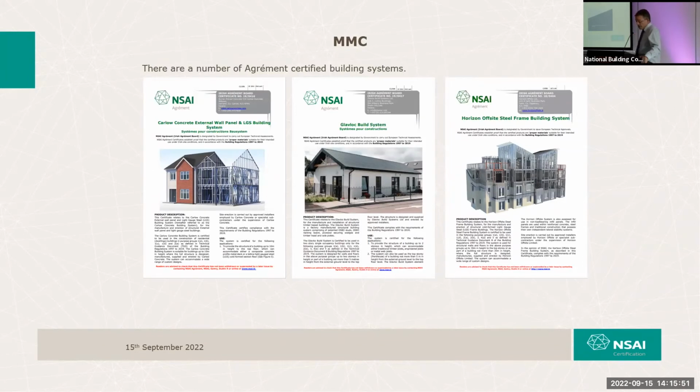Again, it's been said on numerous occasions, if we can just take the accredited construction details and demonstrate equivalence to them, which is a simple process of comparing your detail with an ACD, establishing that the minimum thresholds as described in the ACDs have been achieved, say resistance levels of insulation at window jambs, sills, heads, at pinch points where we have throating at, say, an external wall eaves junction. Not very difficult to do, doesn't necessitate thermal modeling at all, Andrew. And we can go to this advantageous Y value of 0.08.